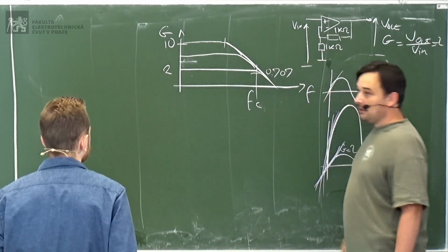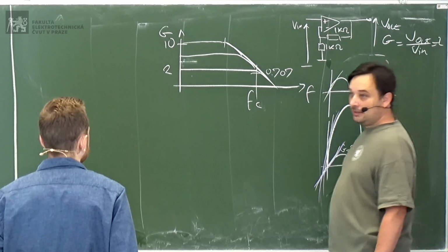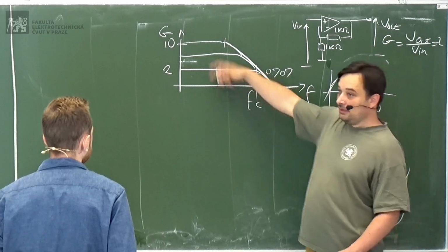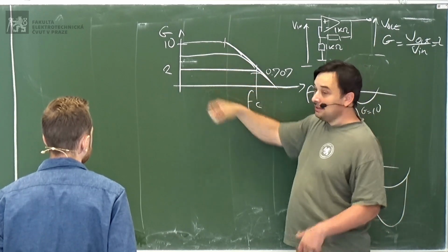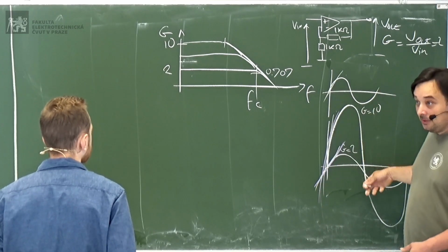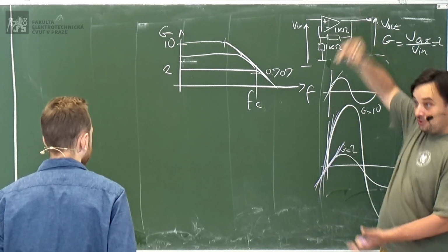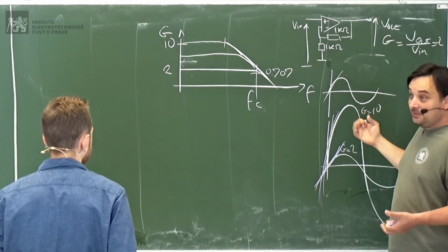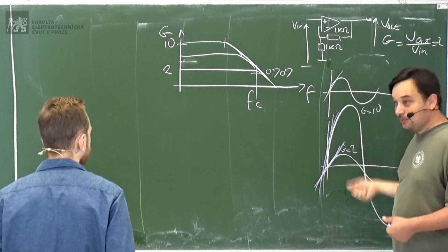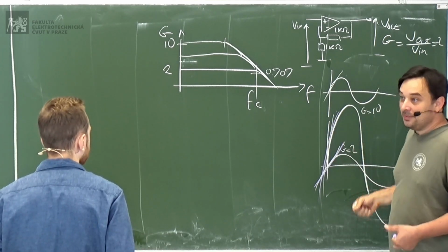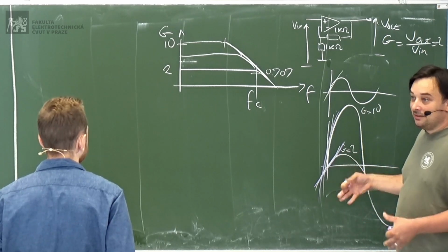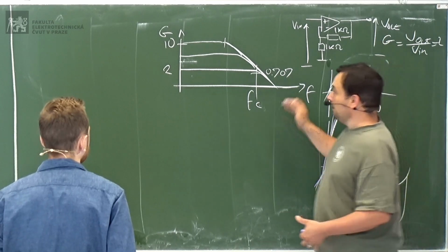So this is what the response looks like in an operational amplifier in a feedback loop. The larger the gain that you want, the faster the output should go to keep up with the input because it has to reach a larger output voltage, but then it means that it will stop being able to keep up with the input earlier, because at the end of the day you still have the same maximum rate of change in the output, okay?